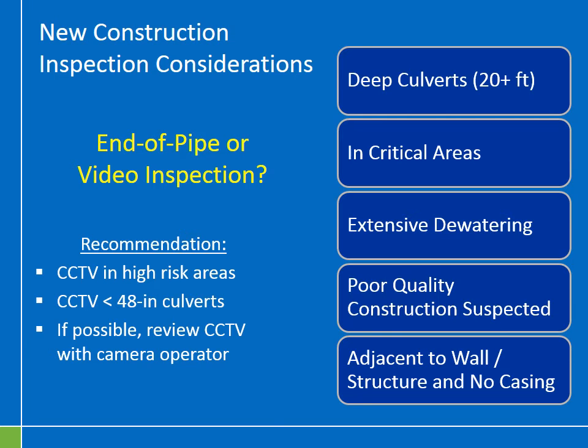Also, just a helpful recommendation, if you're doing post-construction acceptance testing, if possible, review the CCTV with the camera operator at the time of inspection. So if the camera operator misses something that's important, or that you want some additional video documentation, they're already there, so they can get in there and they can get that for you.